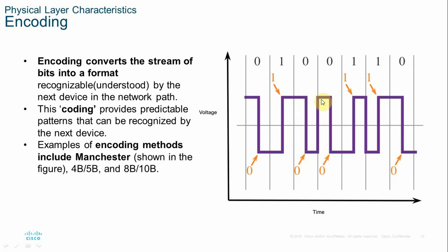Again another 0 means start at the high, at the middle go low. 1 means again start low, at the middle go high. Again 1, so I will start at the low, middle go high. Understand? 0 start at high, middle go low. This is Manchester encoding. If you want more examples, you can ask me in the classroom or in my office.